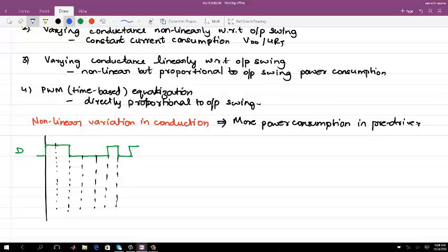Voltage mode equalization is like you can say H of equalizer of n is equal to 0.8 times delta of n minus 0.2 times delta of n minus 1. No matter whichever way you implement this equalizer, right?